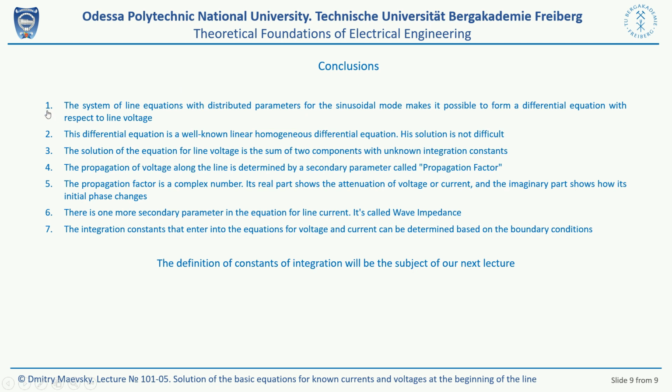Firstly, the system of line equations with distributed parameters for the sinusoidal mode makes it possible to form a differential equation with respect to line voltage. This differential equation is a well-known linear homogeneous differential equation. Its solution is not so difficult. The solution of the equation for the line voltage is the sum of two components with unknown integration constants.